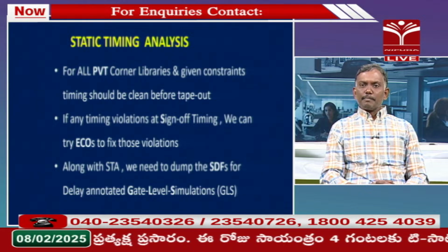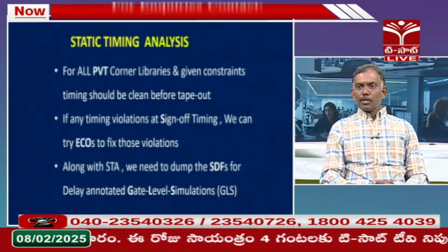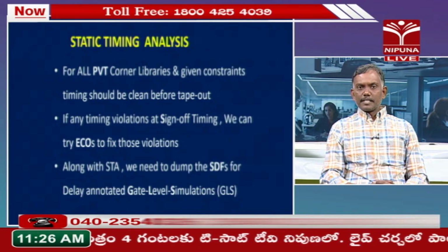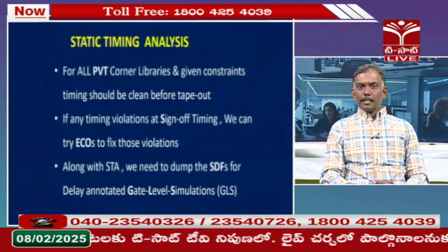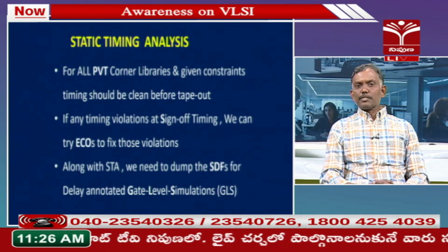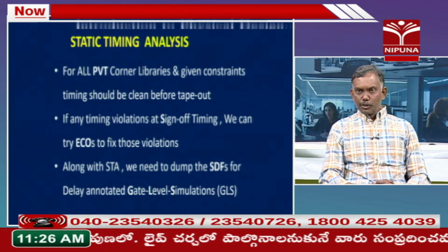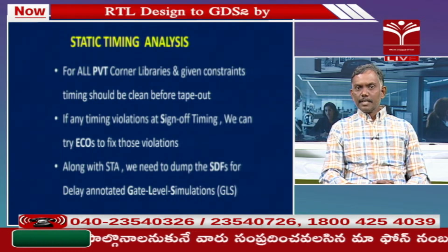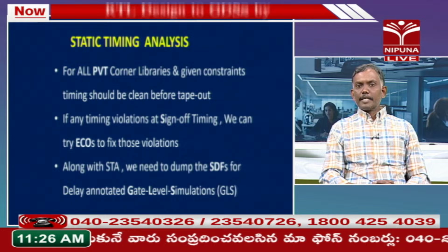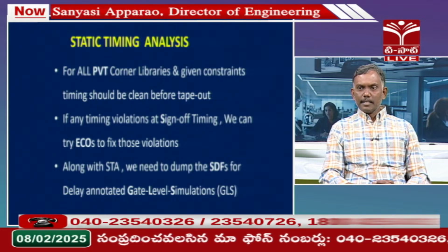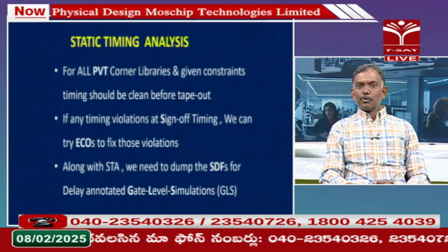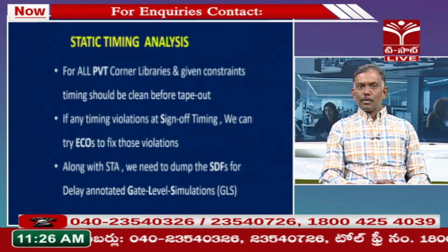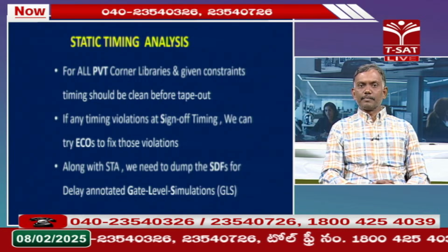And apart from this STA, there is one more check called SDF. We need to provide the SDF, standard delay format, to the verification team. We should provide each and every delay of the gates in SDF format for the delay annotated gate level simulations. This is called GLS, to the verification team, to ensure one more round of check apart from this STA check.